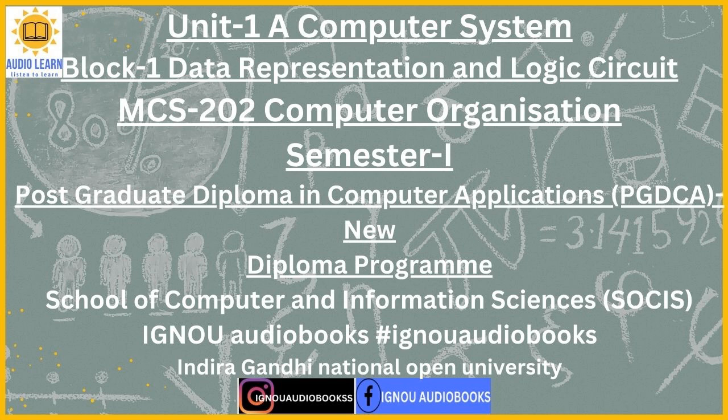4. Load store operation. The processor operates on data managed in registers. Memory access is expensive, so separating memory access from data processing provides an opportunity. With CISC design, the data processing functionality can work on memory directly. The RISC is explained in more detail in Block 3. 1.6.5 Multiprocessor and multi-core architecture. One of the ways to improve computer system efficiency is to have processors with faster clock speeds.